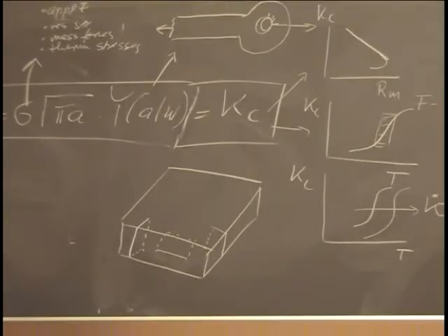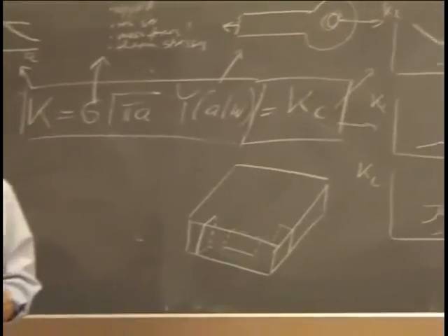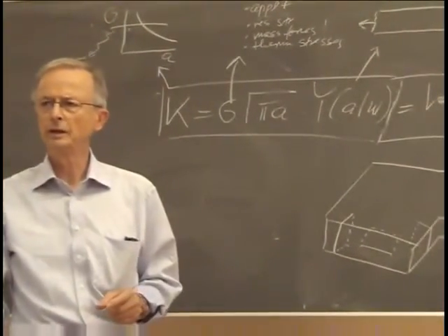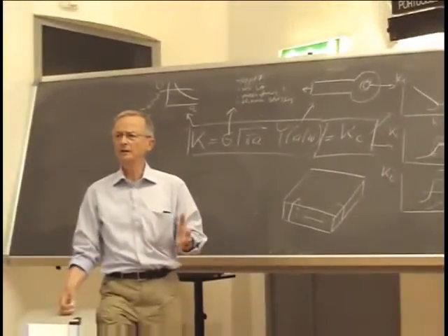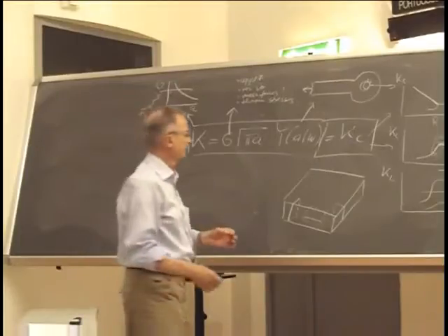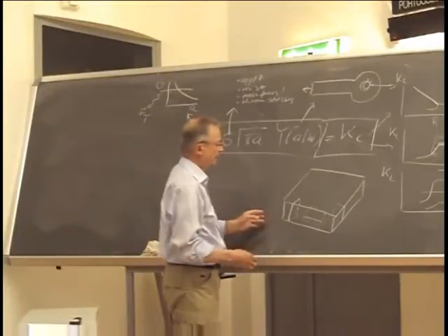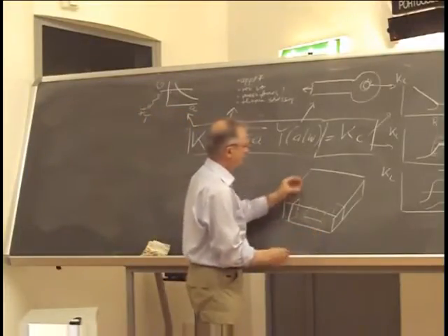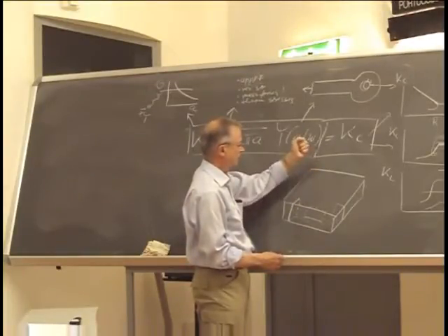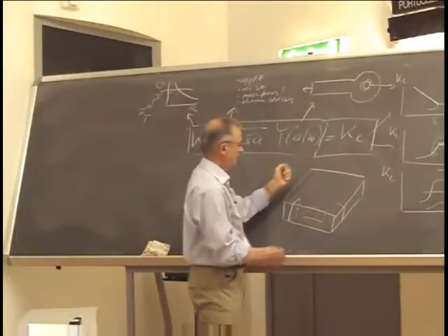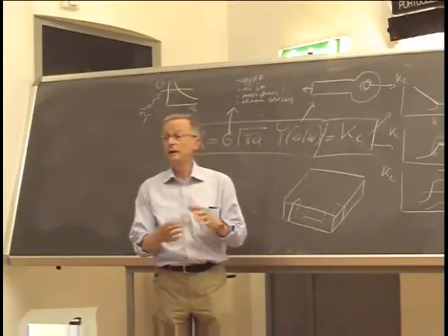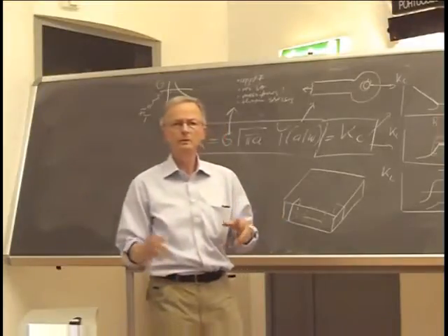And this is why, for example, coming back to offshore, there is a requirement for offshore steels to have very low sulfur contents, because the sulfur creates the manganese sulfides, and they're quite big particles. And in some cases, you have designs with a plate and something welded on, and if this carries a load perpendicular to the plate, then the crack lies here, and you can have total delamination of the plate.